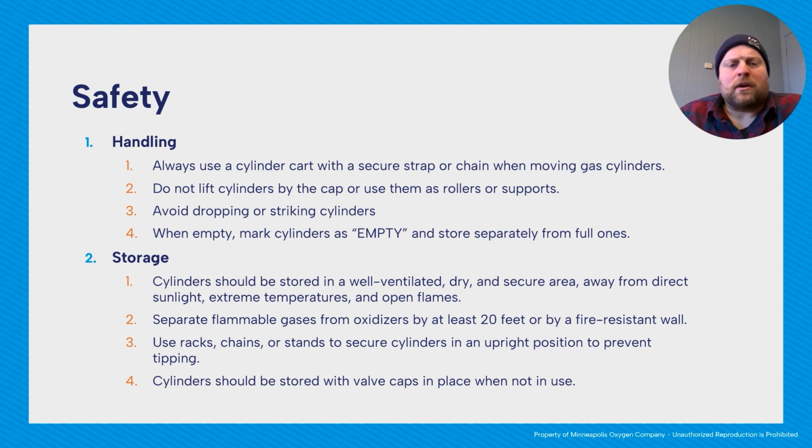You want to always use racks, chains, stands to secure cylinders. We don't just want them standing out by themselves. And the whole point is, with the number 4 here, we got to make sure the valve caps are on. The whole reason is with a high pressure cylinder, you tip it over, you break off the valve, it turns into a missile because all that pressure is going to be coming out of a very tiny little hole where that valve was, and it's going to shoot wherever. So very important. All cylinders we need to secure, but especially the high pressure ones.